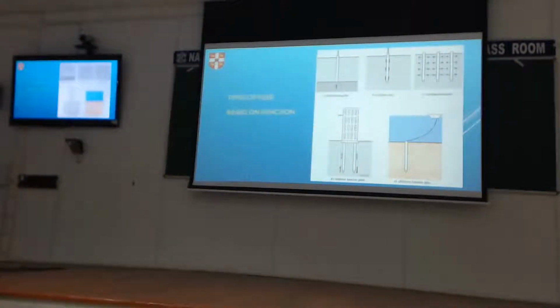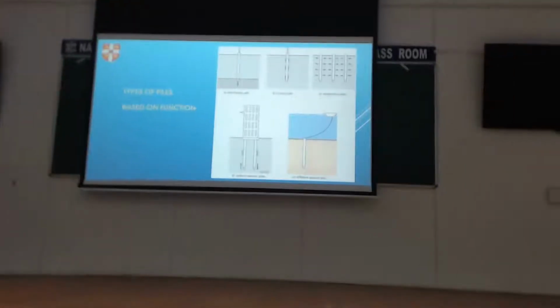It's actually the horizontal stresses increasing that gives you the ground improvement. Because your horizontal stresses go up, your mean confining pressure goes up, and therefore the strength of the material goes up. It's not just the densification that causes the improvement.